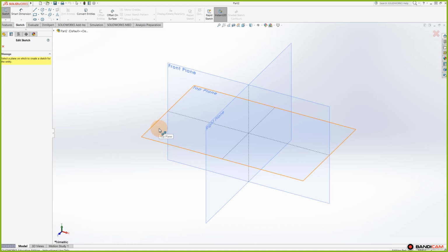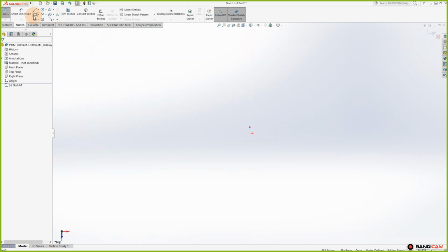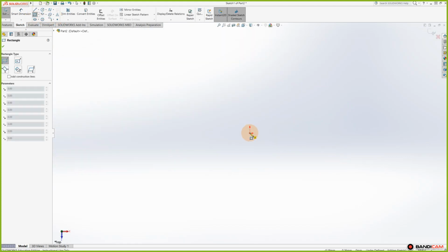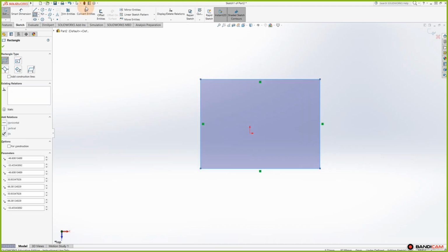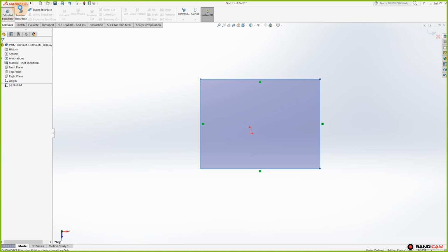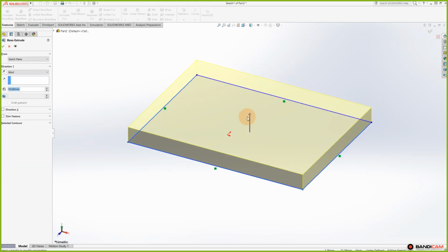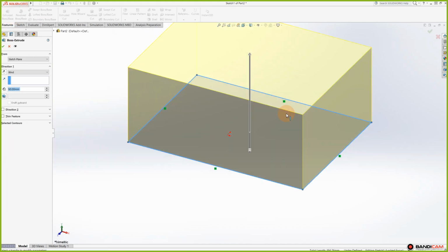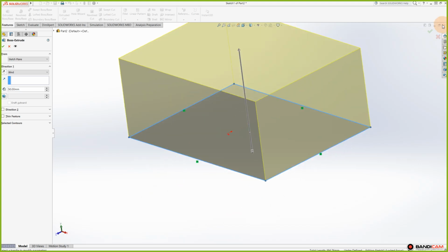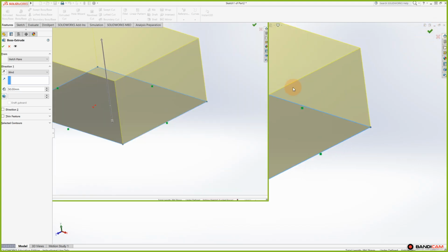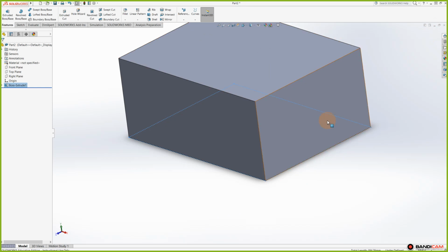Well, in the next lecture, we'll go into more how to start sketching, but I'm just going to go quickly and just do anywhere at this point. Just like that. All right, we have a circle. Let's go extrude it. Yes, you can pull them like that. It is that simple. Press extrude. And now we have a piece that's made.